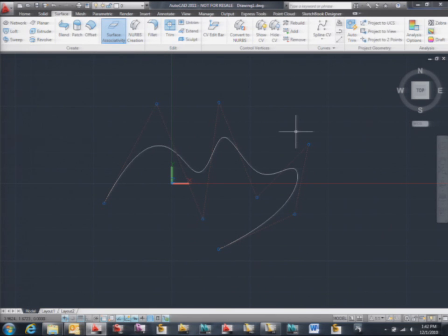I'm going to show a couple of examples. I'll try to see if that can be a little more graphic. None of them is better than the other one. It makes sense depending on the case. If you know that your spline has to go through certain points, fit points is the way to do it, right? But spline through CVs is the best way to define a spline. Actually, if we were not getting into mathematics, because I cannot get into mathematics either, the way a spline is interpolated through fit points is not as accurate as doing CVs, right? In any application. So as a suggestion, I try to work more with CVs than anything else.